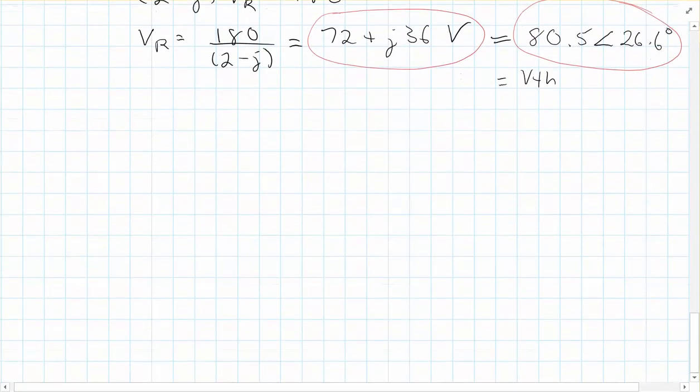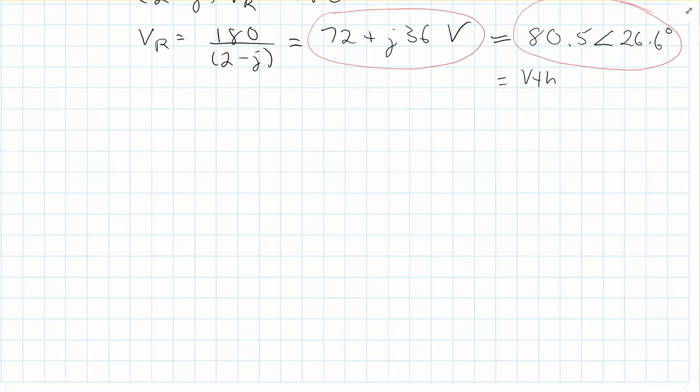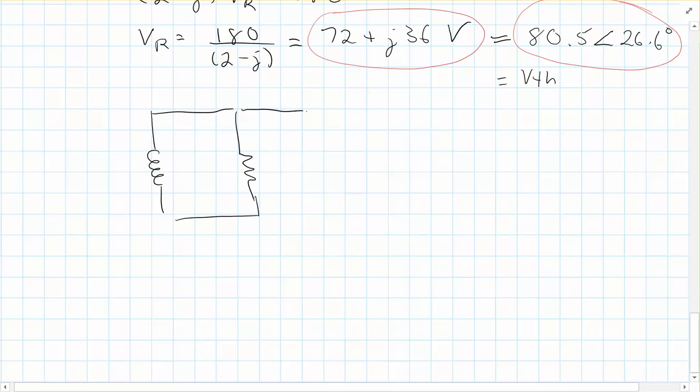Alright, well then the remaining thing we need to do is find Thevenin, the equivalent impedance. Now remember, we turn off the voltage supply. So if we turn it off, it becomes a short. So I'm going to redraw the circuit as if I've turned off the voltage source. And so I'm going to have the inductor, which is now going to be in parallel with this resistor. And then I've got this capacitor. And then here are terminals A and B. And so we wind up with j30, and then 15, and minus j30.